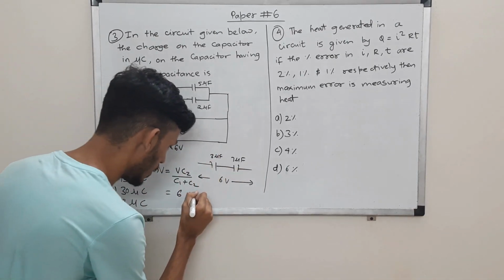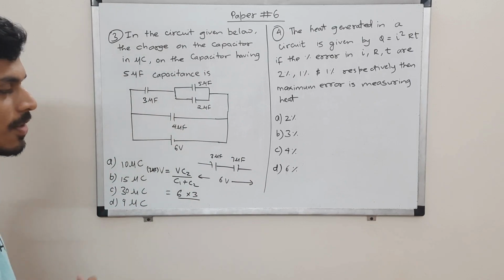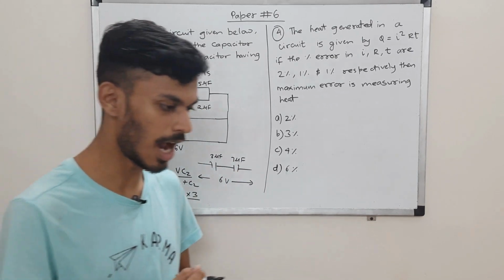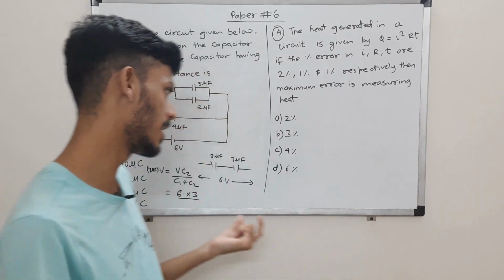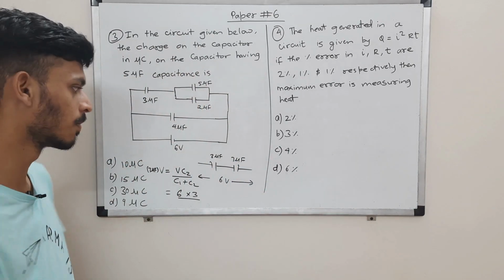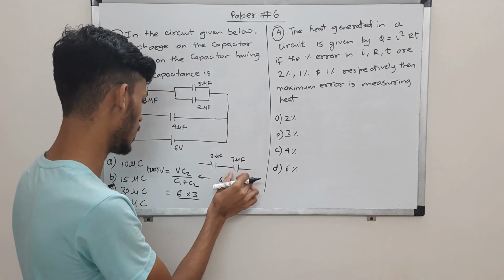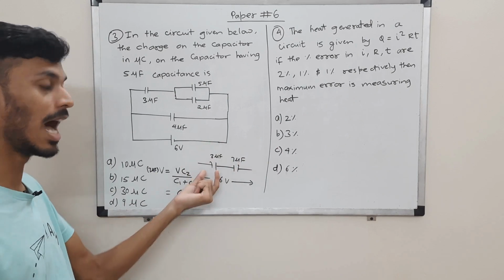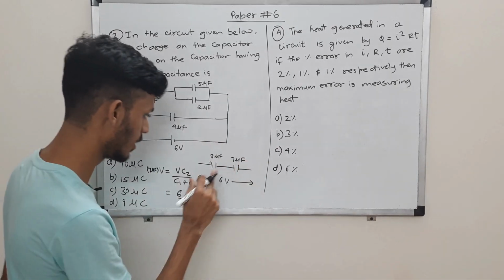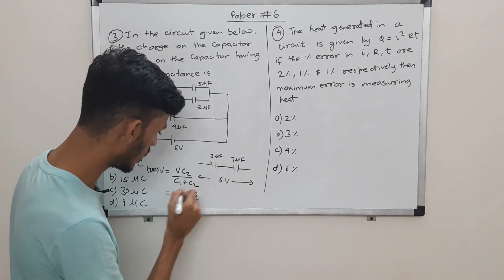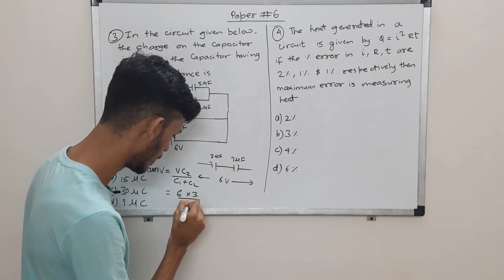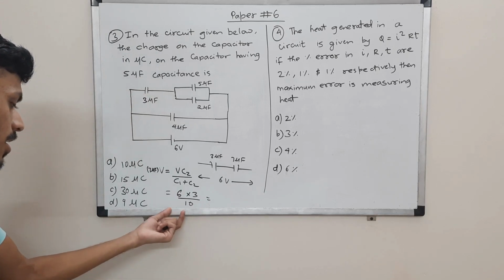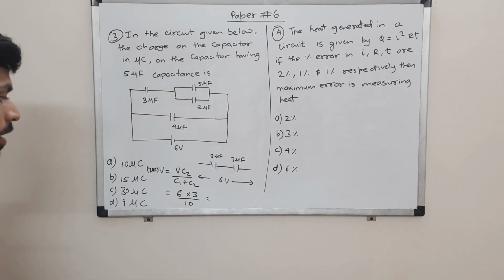So basically it's inversely proportional. When you connect them in series, the charge is the same, and voltage is inversely proportional to capacitance. That's why we are using C2 when we are finding the voltage for this one. So total voltage into the other capacitor, that is the logic behind it. So V C2 upon C1 plus C2, 3 plus 7, that is 10, microfarad cancel. So finally you'll have an answer in volts.